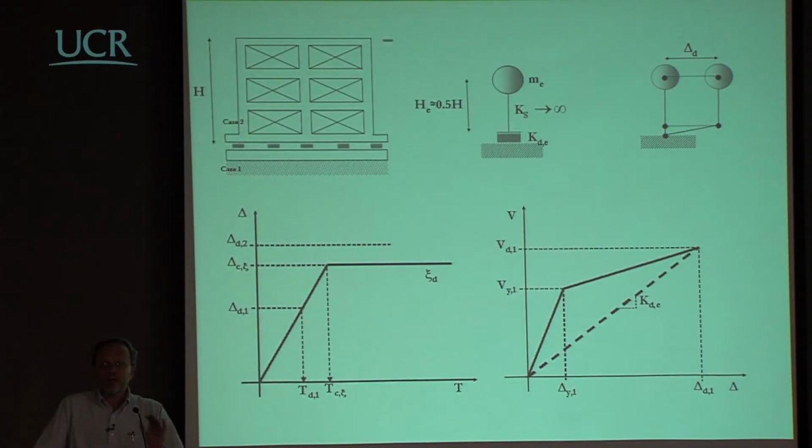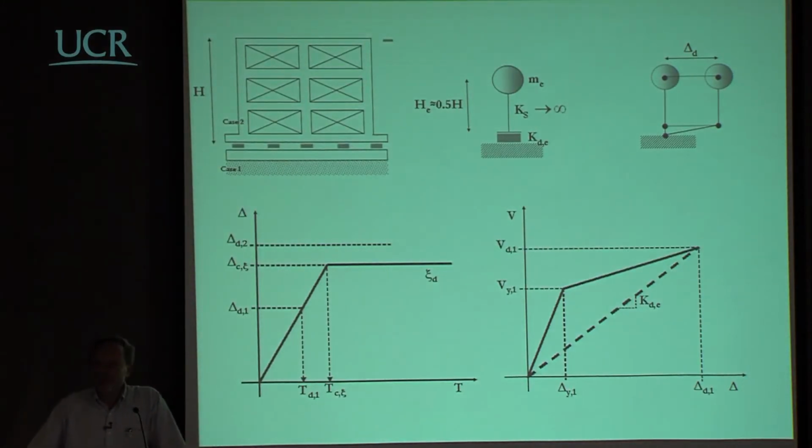So what are you going to do with the isolation system? This is probably the simplest of all possible structures to be designed with a displacement-based approach. You have to assume a certain value of design displacement at the level of the isolation devices. You have to assume a certain level of damping to know what is the action that you have to put there. You will assume this equivalent damping having in mind that if you want to use a rubber bearing, you probably assume maybe 15%.